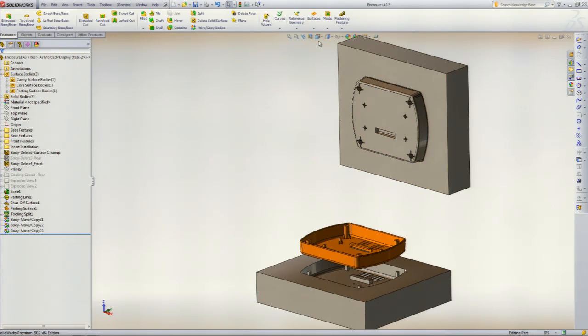It's easy to just go down your mold tools list in the order that the tools are located on your toolbar there. Right, it will show an error typically at the shut-off stage where it's not separating the core and the cavity, where the core and cavity are actually touching. It will show you an error indication at that point. So you have to backtrack and see what feature in your part did cause the problem with the shut-off.